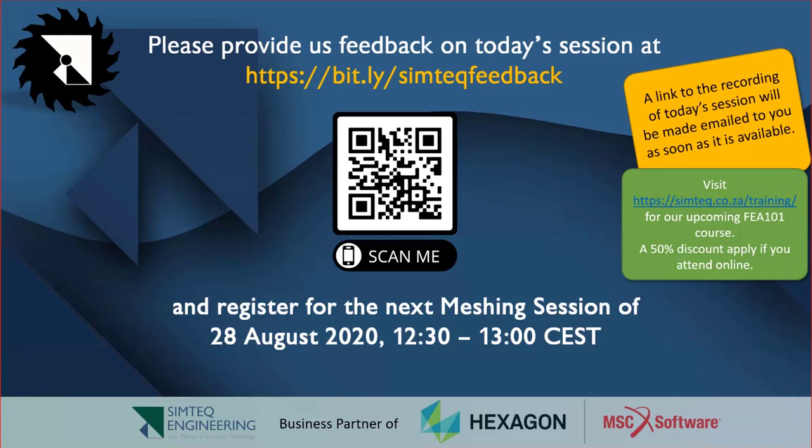I think it will be actually really hard to get to that 0.001% accuracy, but it is possible for very simple structures. Imagine a plate with a hole in it, you're clamping it, and you want to see what the strain state is on that inside edge of the hole. Fine, it's possible. You just need to mesh it fine. But the question is, why do you need to go so far? And the answer is, I can't think of any. Thanks, Gerrit.